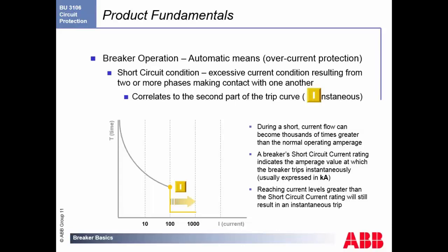So I think if anybody's been in the industry and has ever touched phase to neutral or two phases together, you see the big spark and everything pops. It is instantaneous. Well, that's kind of a misnomer because we do have about a 2 millisecond time delay before we actually trip. And that's just the nature of the physics behind how we trip using the magnetic fields that we are sensing the current going through.